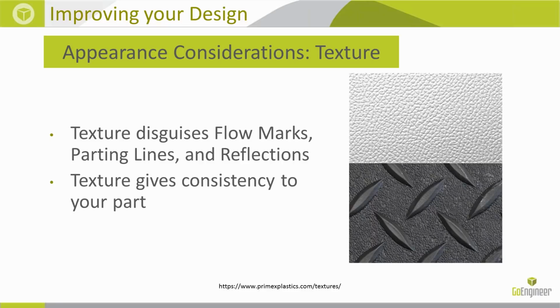So texture does help you, but a lot of people aren't making the decision on texture until later down the road. And that's a problem, because some really aggressive textures require more draft. And you have to cut the mold with that degree of draft. But if your texture requires a larger degree of draft, you might be in trouble. So you want to at least think about texture early on and have a general decision on that.